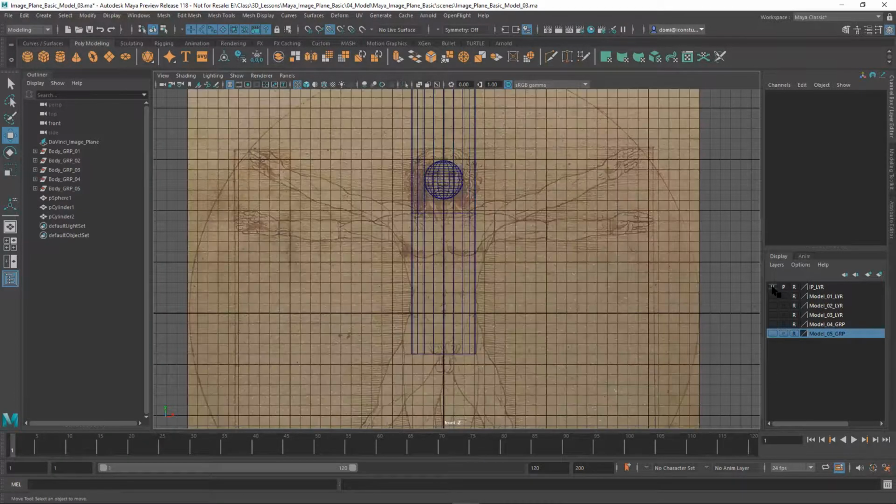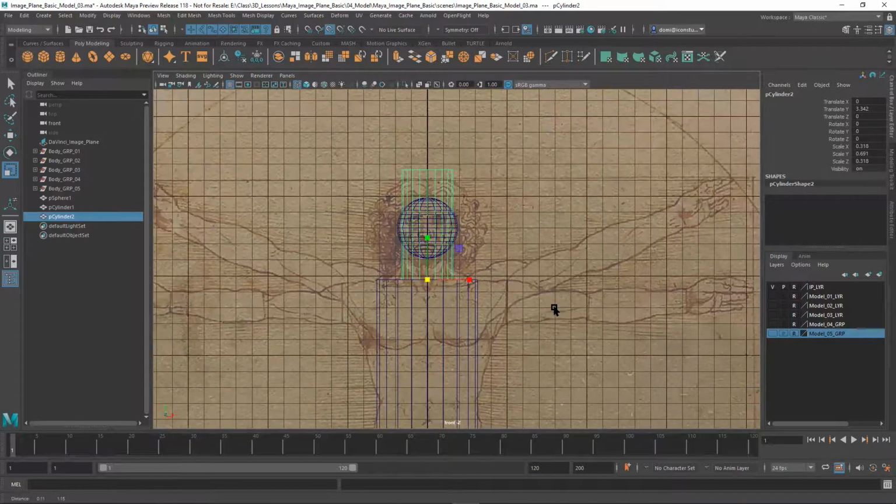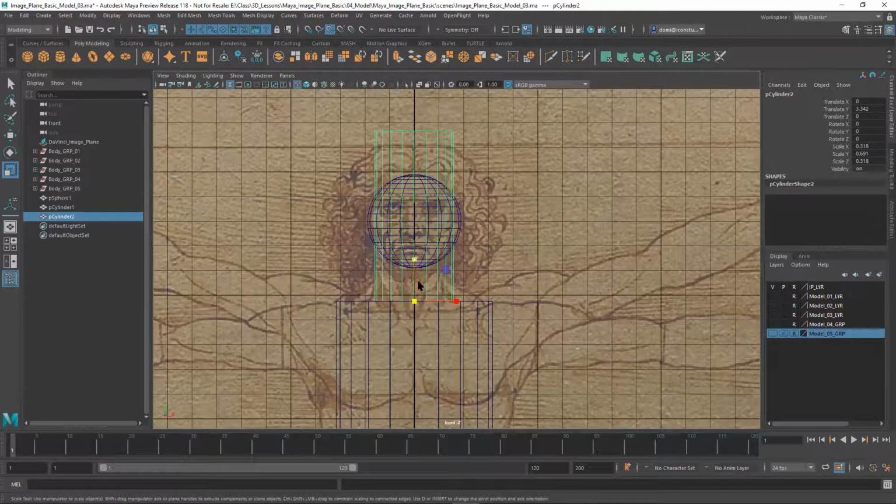So now I'm going to turn this back on so I can see, and I'm going to scale this. Okay, so now I'm going to pick on the scale icon. I'm going to pick the object. I want to scale it. I'm going to scale it globally first. Okay, so I'm going to be scaling it towards what the, let me zoom in a little bit so we can get a better kind of view of the neck. Okay, yeah, that's about right.